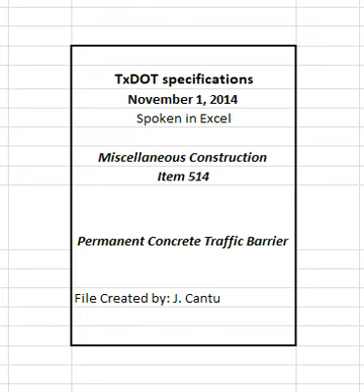3. Construction. 3.1 General. Perform excavation and embankment work in accordance with Item 400, excavation and backfill for structures, except for measurement and payment. Place reinforcing steel in accordance with Item 440, reinforcement for concrete. Welding of additional bars to the reinforcing cage is allowable, if approved, when slip form placement is used. Weld in accordance with Item 448, structural field welding.